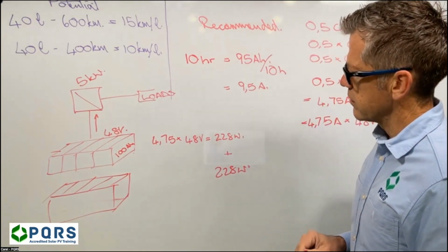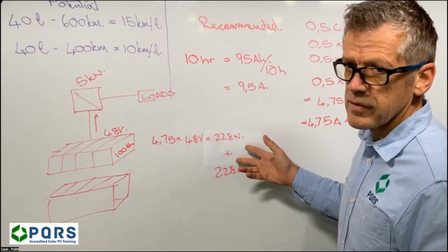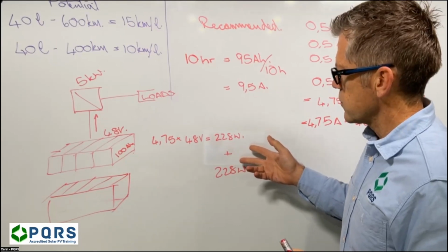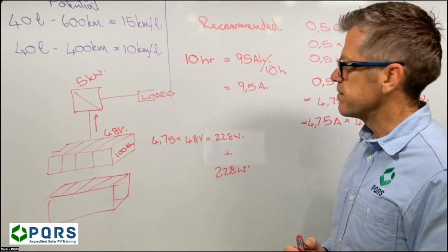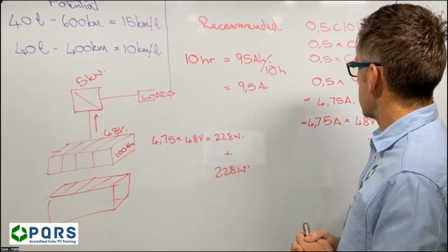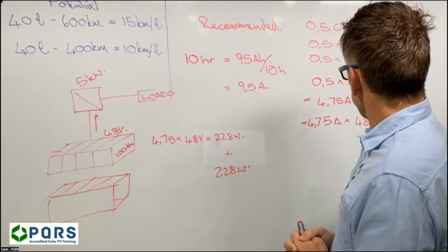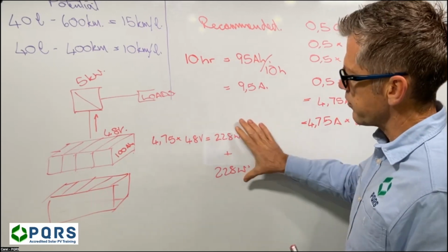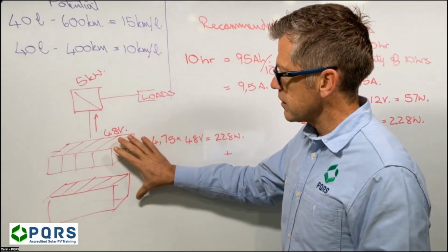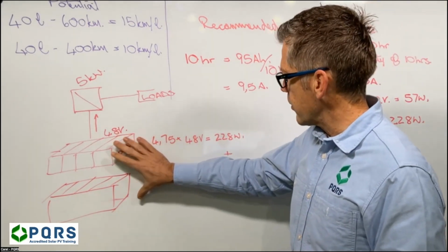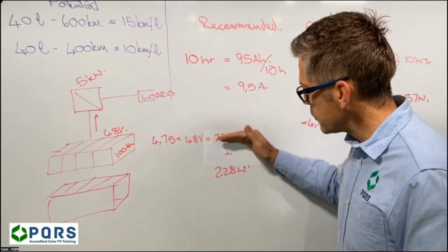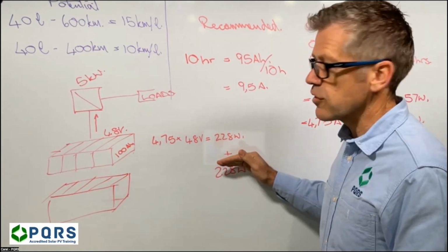It would still only be around 500 watts. That's not very good. Okay, so that is if we use a different type of battery. This is for a 100 amp hour battery. So if we wanted the battery to last longer, we would have to reduce the rate at which we discharge the batteries.